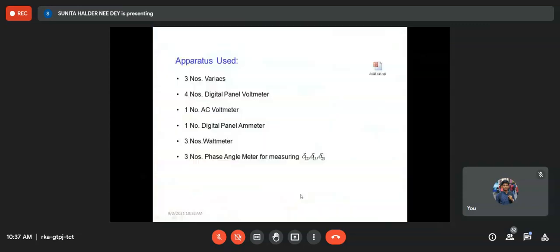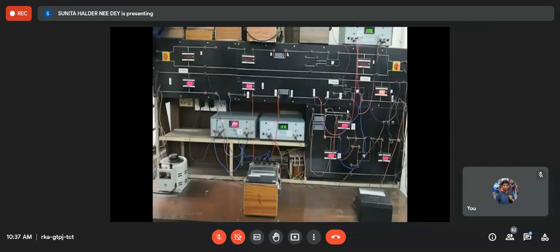So this is the actual setup. Here you see these boxes are phase angle meters. It is showing 23.4, 13.5, 12.05, and so on. And here some LED is glowing. You may notice I am pointing with the arrow. This LED indicates lead or lag. There are two LEDs corresponding to lead or lag. From there we can identify whether the voltage is lagging or leading.